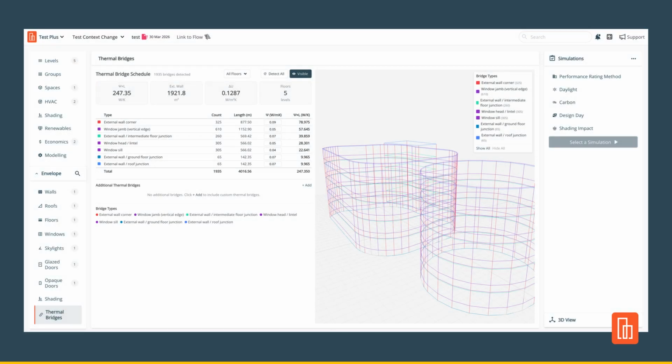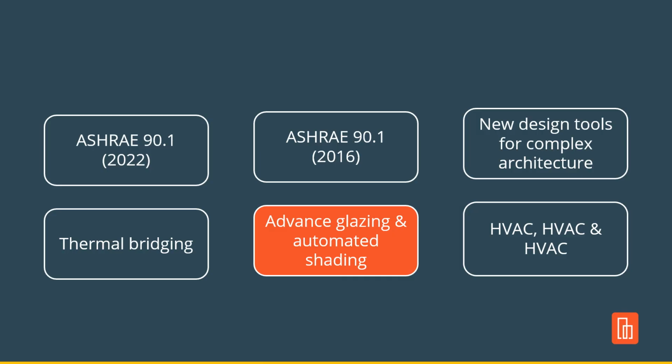Now there's two aspects to what we're doing here. Is the automatic detection of thermal bridges themselves. That work's already done, ready to go. Then there is the other aspect of the direct finite modelling of thermal bridging. That's also in play here. So we're also going to enable you to do direct thermal bridging on the platform in order to generate those psi values or chi values in order to input into this process. So again, we are a platform, and that's why we're looking at that.